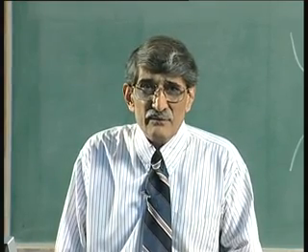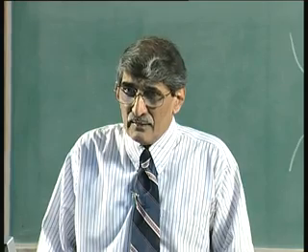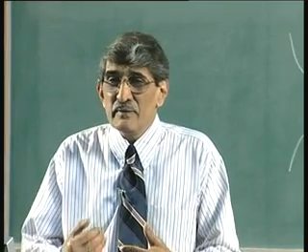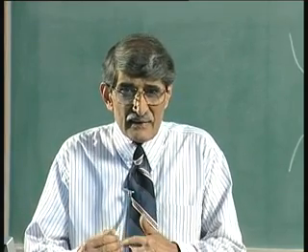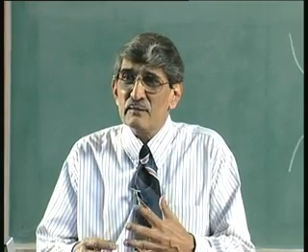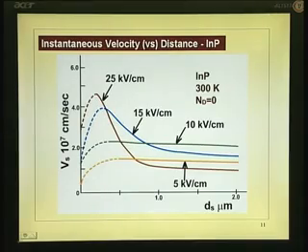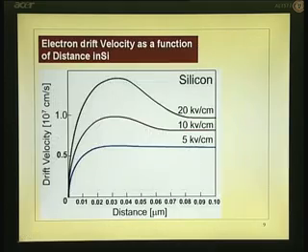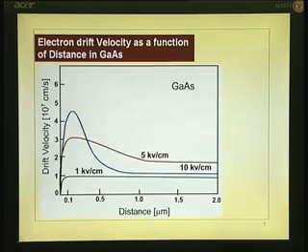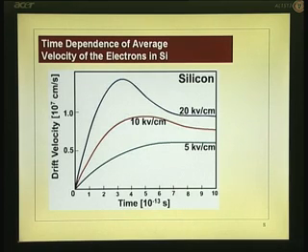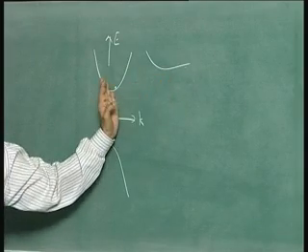It will not be a transfer from lower valley to upper valley; it is the difference in the relaxation time between the energy and momentum. It takes a different time for the entire thing to stabilize. Because of that, even in silicon you will see some amount of transient, that is what I projected here. But please note the time frames and also the distances. You do not have to deal with so much difference in momentum in silicon. Here you have to deal with a lot of momentum difference.